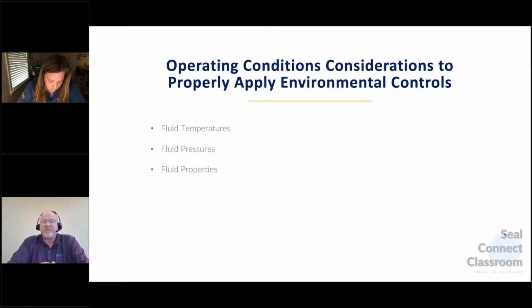Understand, no seal is 100% leak free. Seals leak vapors. And what you're doing is you're getting a pressure drop across that face to the atmospheric side, and the product you're pumping will go to a vapor. That's the reason we have double seals and single seals.